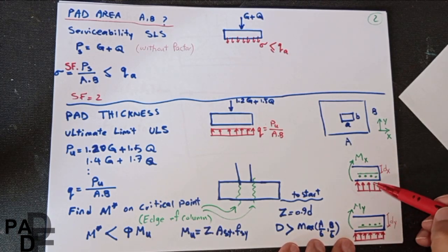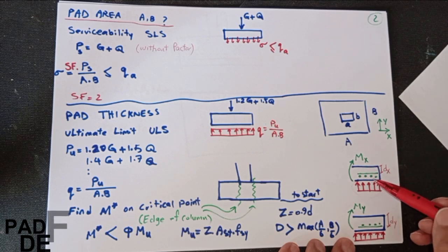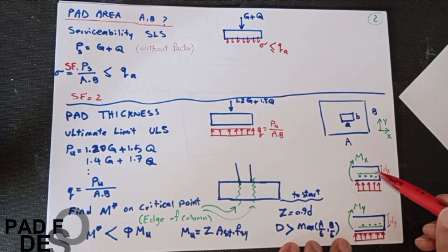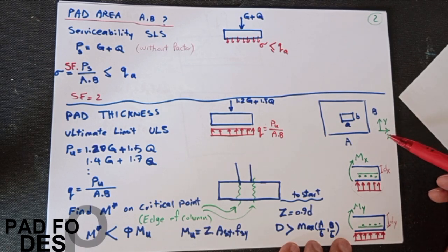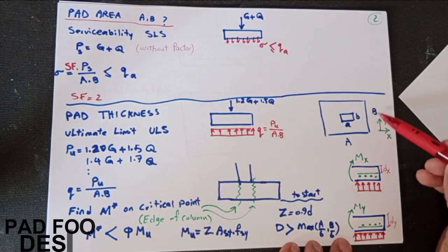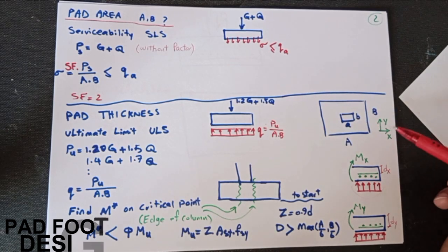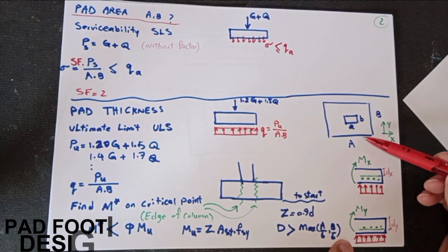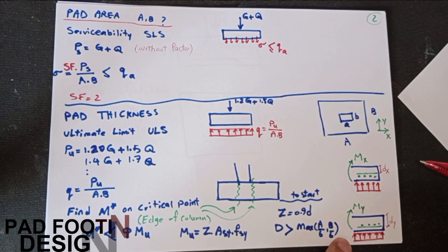point. And then we're going to have simple section bending for reinforced concrete, and we can define the longitudinal reinforcement in each direction. Just remember, we have two ways, X and Y. We need to check both ways for bending. If A and B, and small a and b, are not the same, we may have different values of M for different directions. So we need to check both directions to have a safe design or consider the critical one.